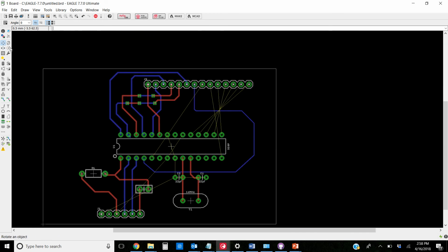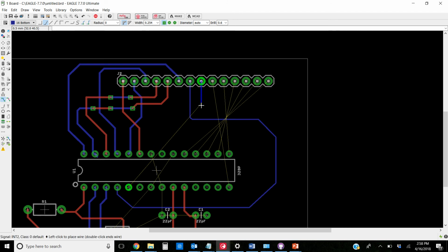All right, and then we can do the same thing, go back to routing, and we'll follow the same path here. Oh, we get stuck again, right? And so we have our options to cross over. But instead of crossing over, let's just hit escape. Let's rip this up and just use the top layer, and then we can cross over up here. Click on it, change over to the lower level, and then finish it, right?